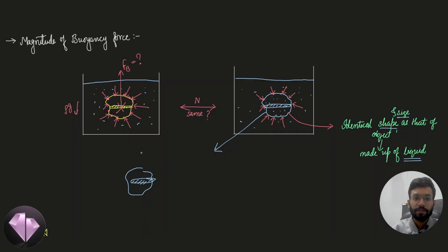And the fluid element is experiencing these normal forces because of the surrounding liquid, right? So surrounding liquid की वजह से ये सारे normal forces हैं, जिनकी वजह से there is a net upward force which is Fb acting on the fluid. The fluid is also experiencing a downward force which is dm into g. So this is mass of the fluid into gravity.